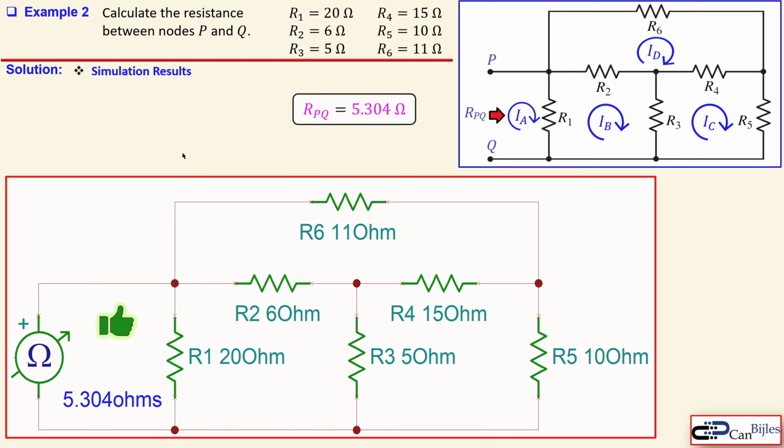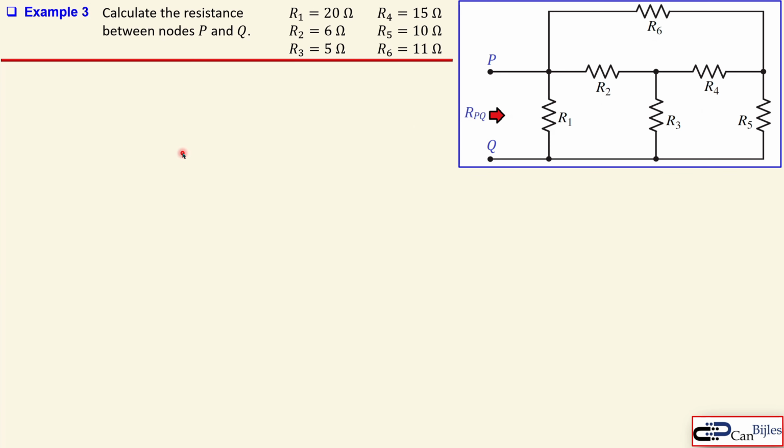Now we will do the exact same circuit using another method. So in the solutions we will see that we have now a second method, which will use the node voltage method. So we will set up the node equations for our first step. For that we need to designate some nodes. I will designate this node A, another one here, node B, and also node C.